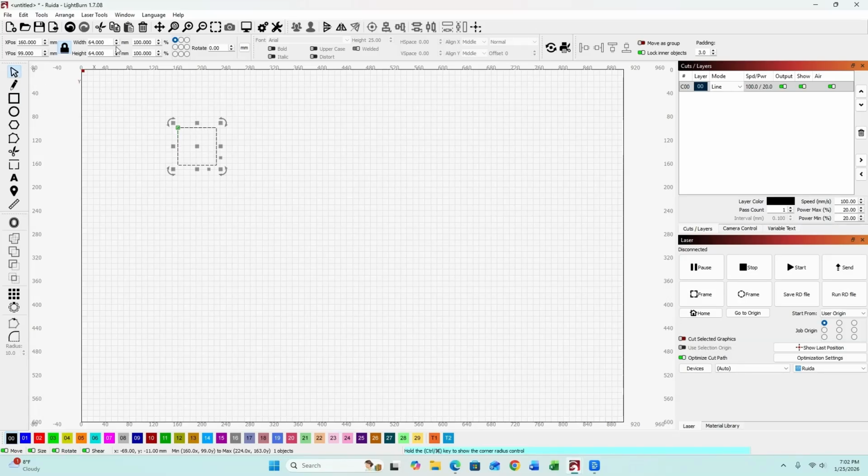Now it's in millimeters, as you can see, and I've told you before, I'm not a millimeter girl. I need to visualize things in the inch format. I can't do the metric system. What I'm going to do is go in here. I want this little block to be 1.5 inches. And so I'm going to do 1.5 IN. And there, you see, it just adjusted it down for me. I want to move this more in the center so it's easier to build off of.